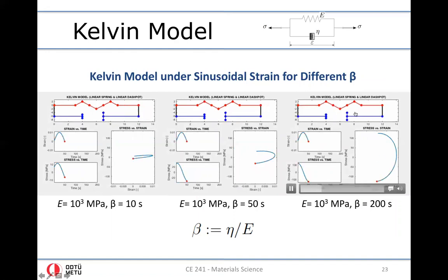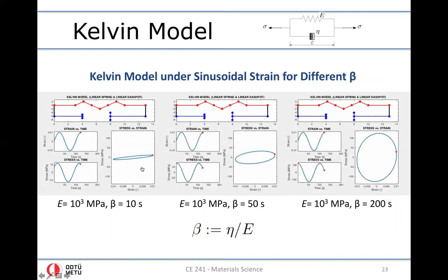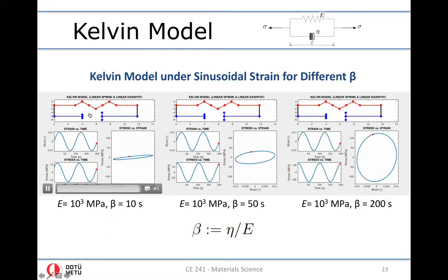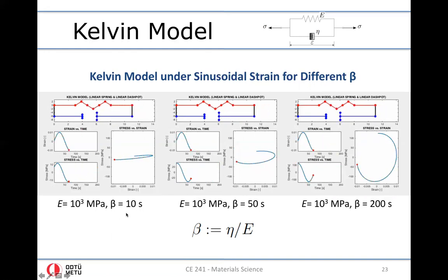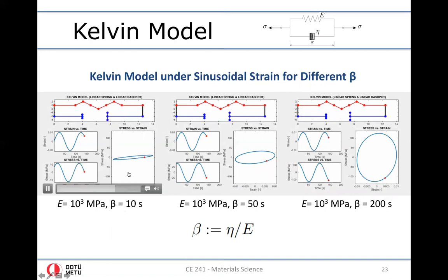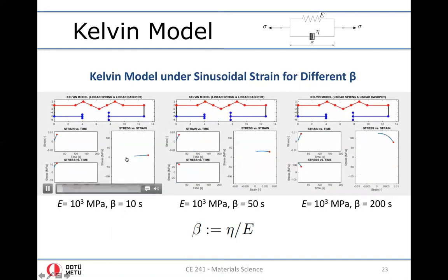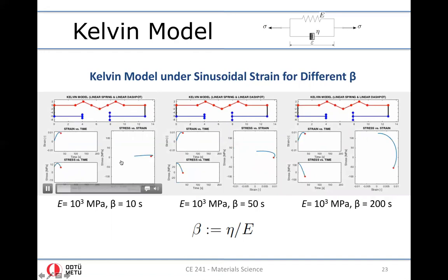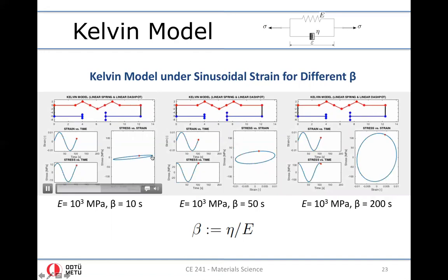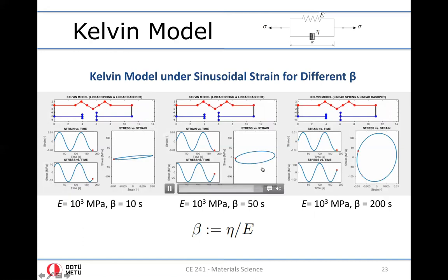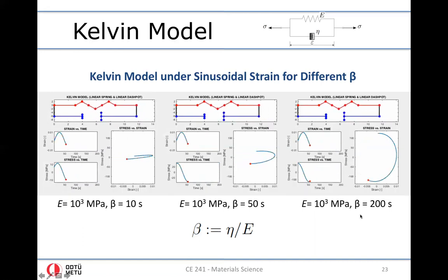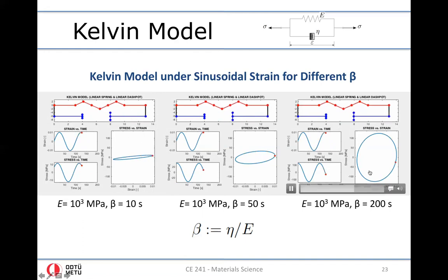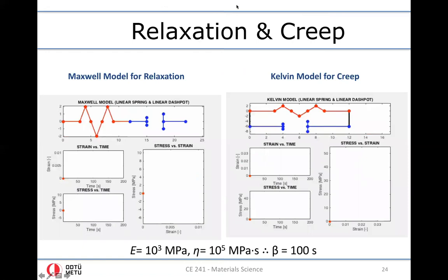When it comes to sinusoidal loading, you see here, as the contribution of the dashpot decreases by decreasing the viscosity, we see a smaller hysteresis. In other words, a smaller amount of dissipation, and less magnitude in the stress. And when you increase the retardation time, the stress response actually becomes stiffer. Okay.